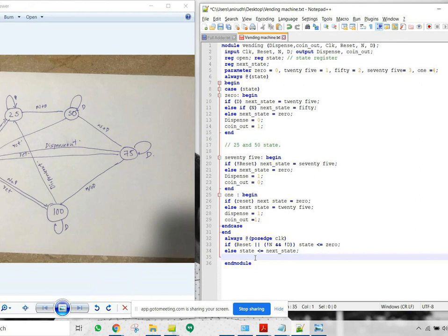The Verilog design, you are naming it as vending machine.text. It should be called vending machine or whatever dot v. Dot v extension is for Verilog. It should not be a text file. It should be a dot v file, v for Verilog. Then your Notepad++ that you are using will also show the color coding scheme even more correctly. It's showing right now, but it can show even better in that case.